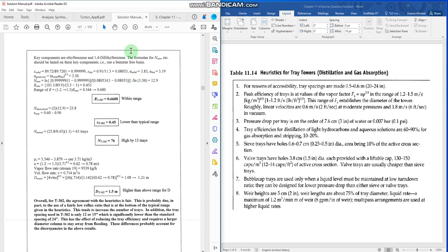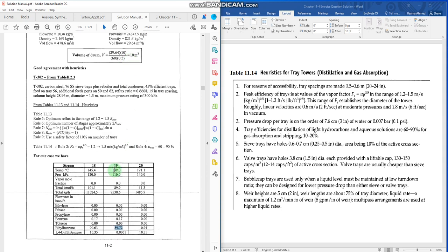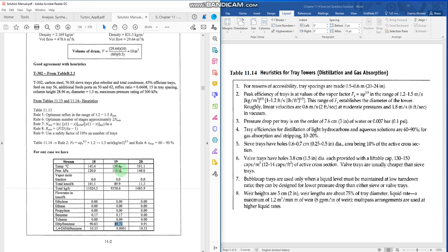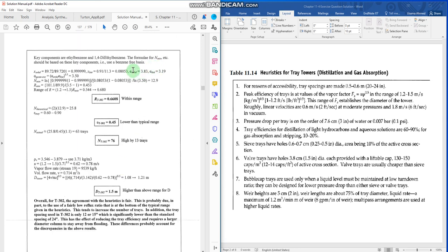You are provided with the temperatures here. Okay, so you can use this temperature equation to get the value for the pure vapor pressures. Okay, and from there you can get the value for alpha overhead and alpha bottom. Okay, so you must have studied this in the stage-wise distillation process also.